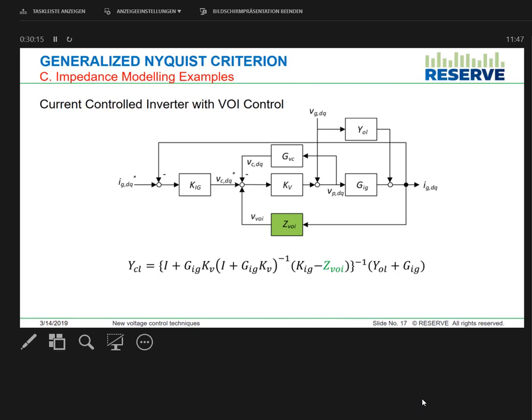So you can see here how this term that I newly introduced, because this is my term, this is how conventionally inverters are done, and then suddenly I introduced this term, and now you can see how it affects the performance, or how it reshapes the impedance. So this term is nothing but the external current controller. It modifies the external current control term.